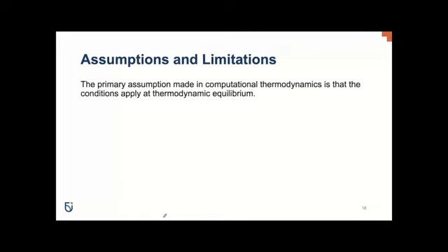There are a number of assumptions and limitations that are applied in this form of modeling, as is the case with every form of modeling simulation used in any type of engineering or scientific analysis. The primary assumption made in computational thermodynamics is that the conditions apply at thermodynamic equilibrium. What is worth remembering is that the models themselves are empirically based, which means that the models are derived directly from experiments.